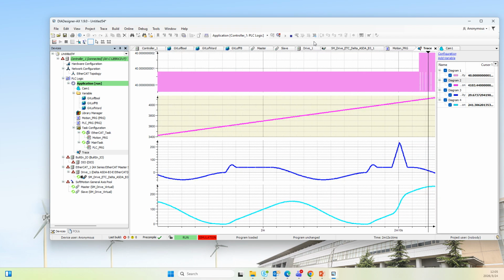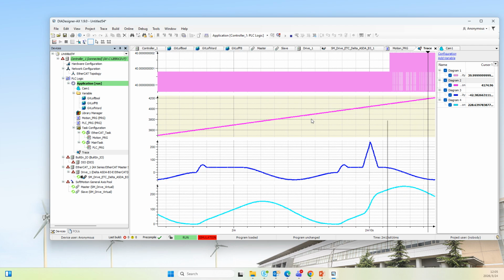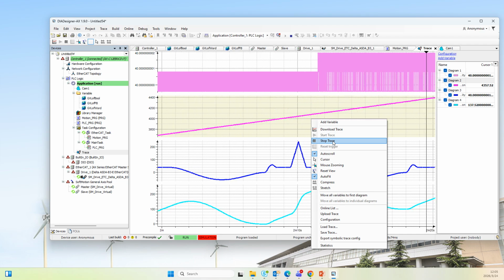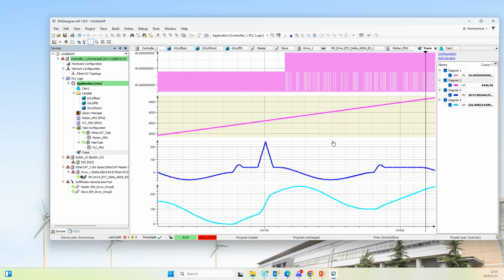Okay, you can see just now when I enable the superimpose for the slave, compared with this part, actually here should be the constant speed, but because you want to compensate the 100 distance, the slave needs to add an additional speed, so the speed will increase to catch up the 100 distance.